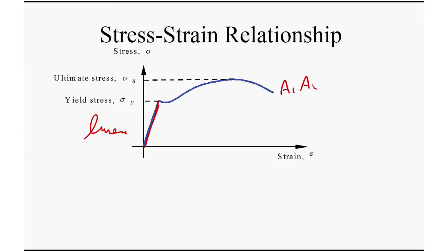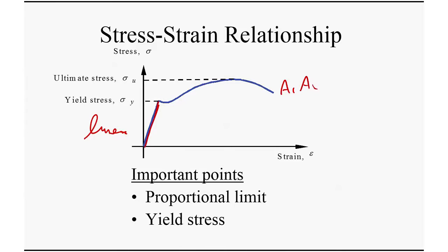What's the relation between stress and strain? It's linear or proportional. That's the same word, meaning the same thing, right? So we have a stress-strain relation in this range, right? So that is actually my next slide. Okay. So before I show this relation equation, now a few key points. Let's just review what you learned before. One is called ultimate stress. So this point, how high a stress you can go for this material. Another one is the yield stress. This is the point. So we always use this as our limit. So you never design anything so that stress goes beyond the yield stress, because that's what we consider failure, right?